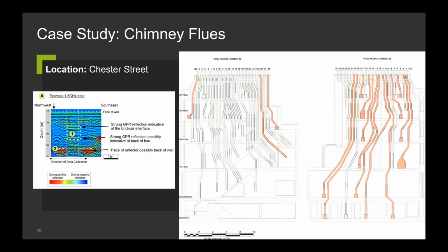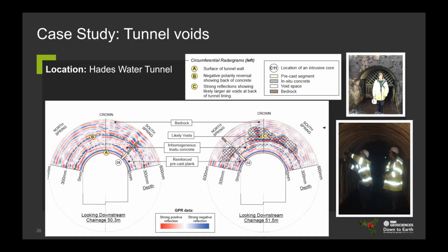At certain times of the year, the brick to air contrast is one of the strongest concepts in GPR, so it's going to produce a really bright reflection. If there's any material stuck in what should otherwise be a hole, this would then present as a weaker contrast, so a fainter reflection in the GPR, although this will obviously depend on the extent of the blockage or the damage.